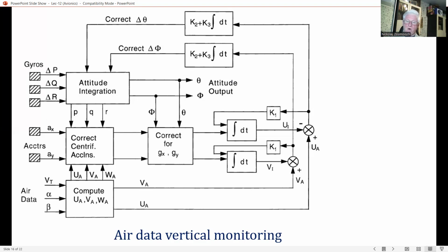Any acceleration of the reference frame due to changes in the wind velocity, however, can introduce error. The assumption is made that the air mass accelerations generally appear as gusts of comparatively short duration, which can be effectively smoothed by the air data or inertial mixing.